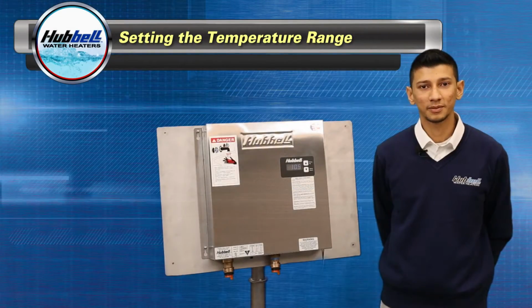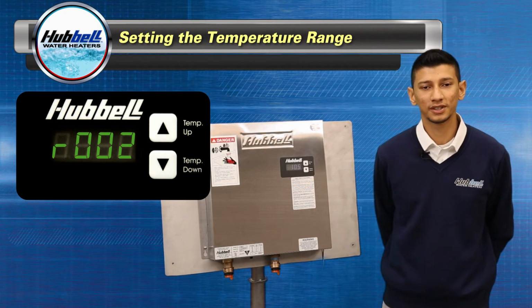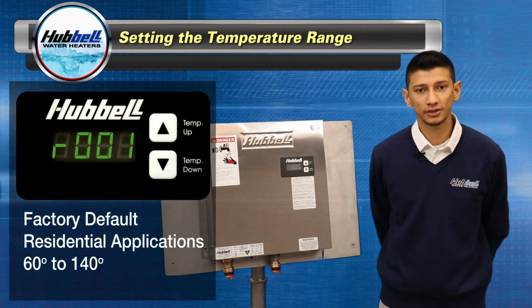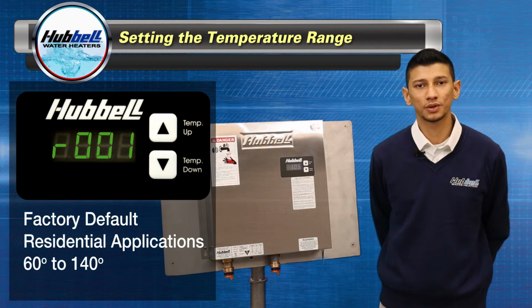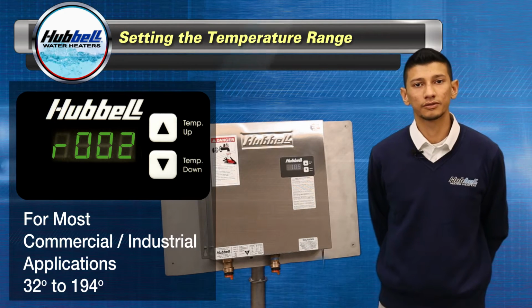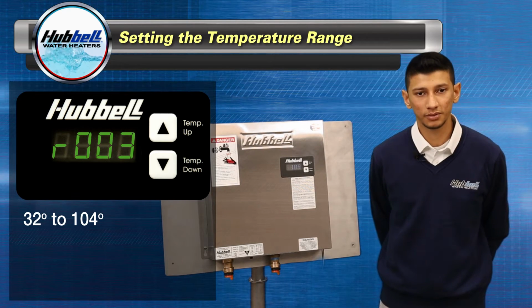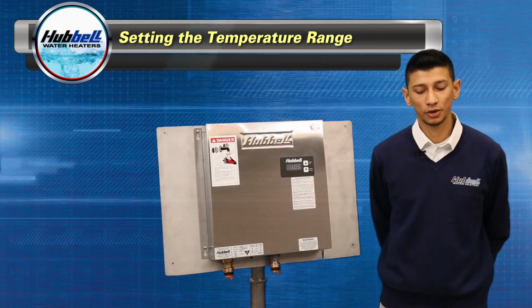The next parameter is the temperature range. There are three: R001, R002, and R003. R001 is the factory default and set for most residential applications. It provides a range of 60 degrees to 140 degrees. R002 provides a range from 32 degrees to 194 degrees for most commercial and industrial applications. R003 provides a range from 32 degrees to 104 degrees. The value should be set for the appropriate range based on your application.